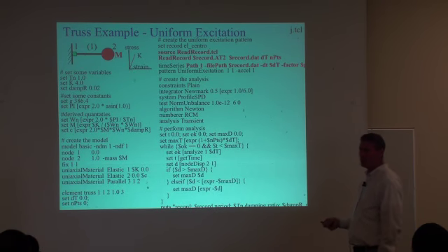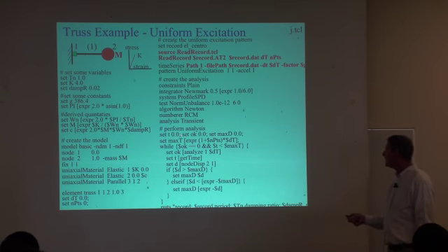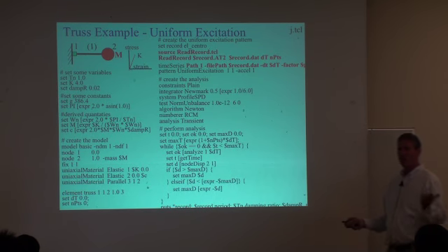So what this is going to do, it looks complicated. We're going to start out with t is 0, set ok to be 0, set my maximum displacement to be 0, and then it's going to run through this. While ok is equal to 0, I can define the rest of my max time, do one step, get the time, get the displacement, and then check if the displacement is greater than the max displacement. If it is greater, at every time step we're just setting the current max displacement equal to whatever displacement came back. And then when I'm done, I put out the record, period, name, and some other information.